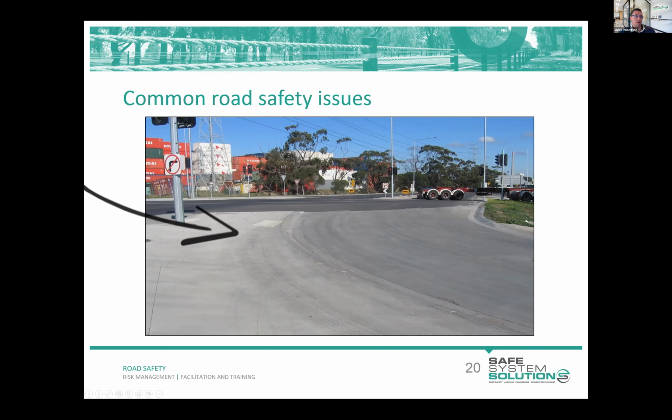On the other side of the road, however, the pedestrian might be a little more out of sight, and this is the area where the rear axles of a turning truck will end up if it takes an inappropriate line. This is a common pedestrian safety issue, that a pedestrian waiting at an intersection corner is struck by the rear end of a turning vehicle, where the rear axles encroach. The rear axles take a shorter path on a smaller radius than the front of the vehicle, and there is potential for the pedestrian to be struck.